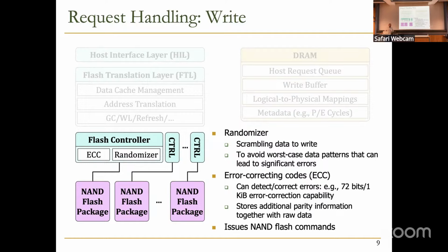So, think about it. For example, if there is a data pattern, let's say all ones, it's not just one row. There might be several rows, and some combination of data pattern across these rows can cause you to lose charge faster. I'm thinking about retention failure. So some data patterns can cause that.